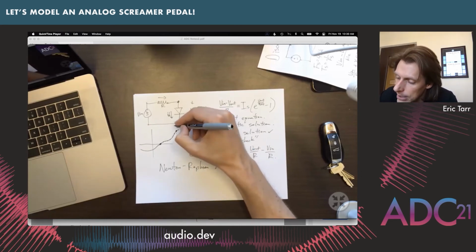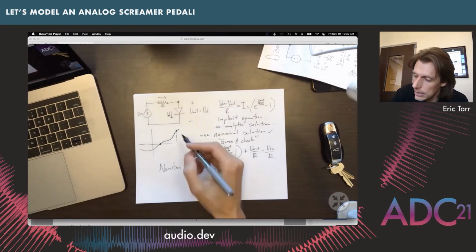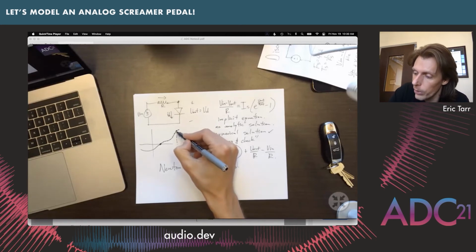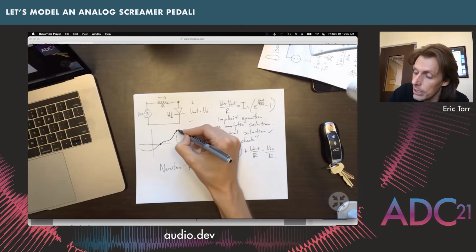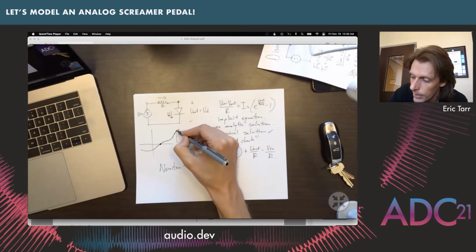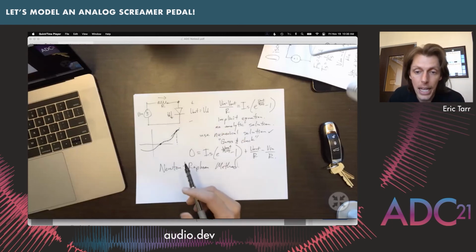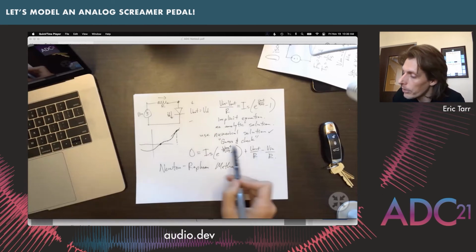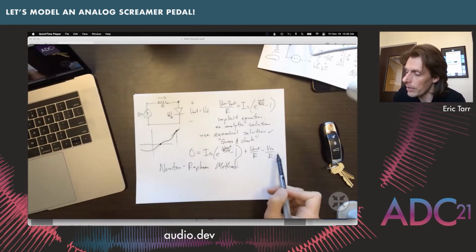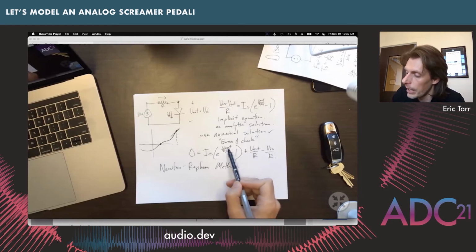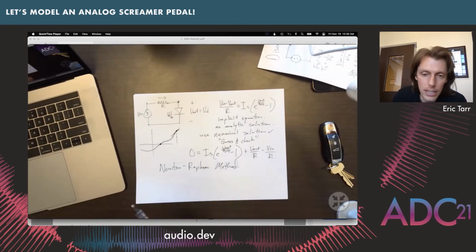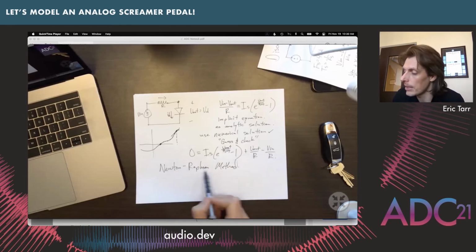One of the things that I was discussing is this idea of going up or going down. In calculus, this concept is we want to move along the slope or look at the slope, where we could say if the slope is positive, then we want to move in this direction. If the slope is negative, we want to move in the other direction. And so there's this idea of this derivative that we can have, which is the slope at this particular point where we're at in the beginning. And with most of the equations that we come up with for circuits, we're able to find the derivative at this particular guess that we begin with and use a derivative to our advantage. And that's what the Newton-Raphson method is all about.